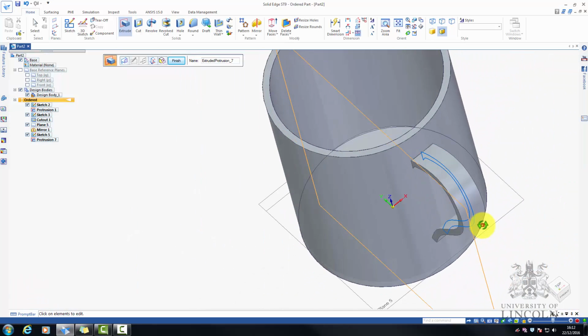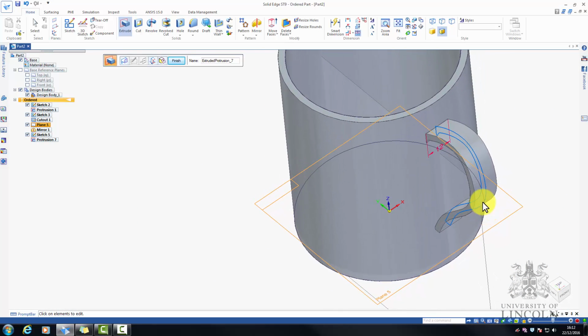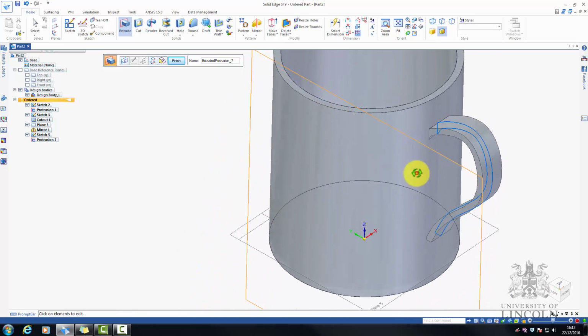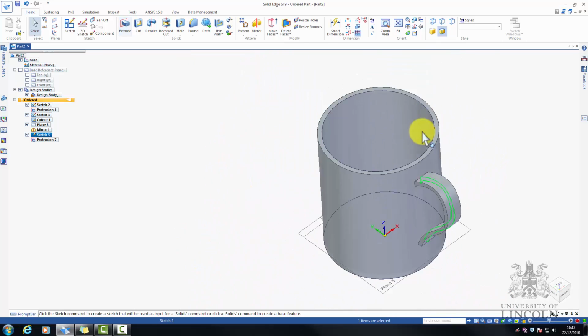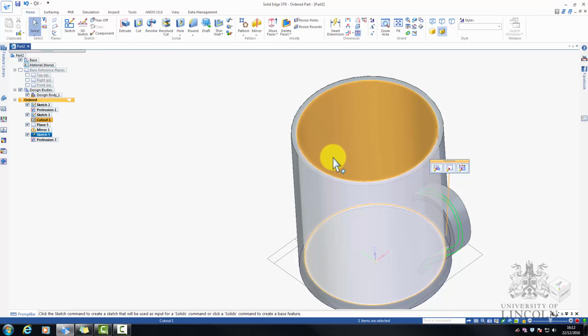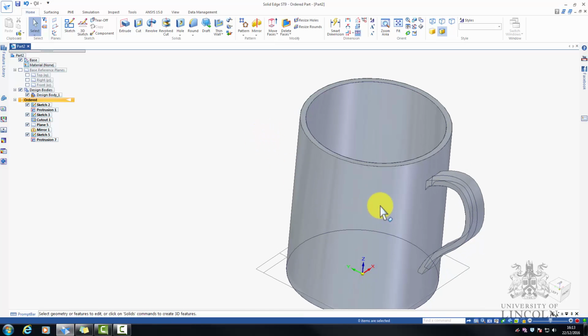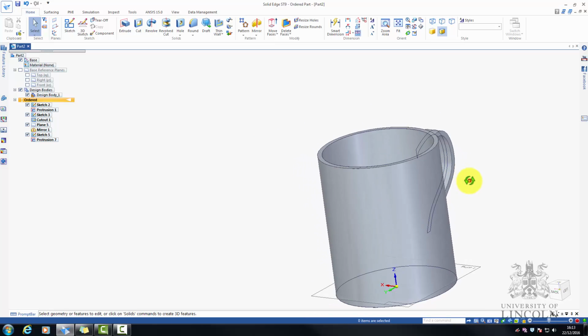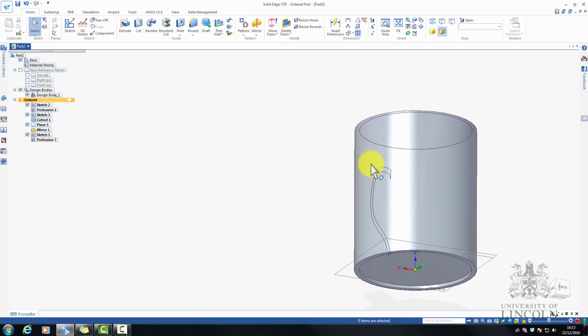It's not very elegant. It would have been better for us to perhaps try another technique I'll show you later on with a rail. We could run from the curved surface outwards. But with just extrusion, that is pretty much the limitation of what we can achieve. I could then tidy this shape up with some other functions like 3D filleting tools and 3D chamfering tools, but you do get the impression of the complexity of the shape here, and it's a reasonably fast process.